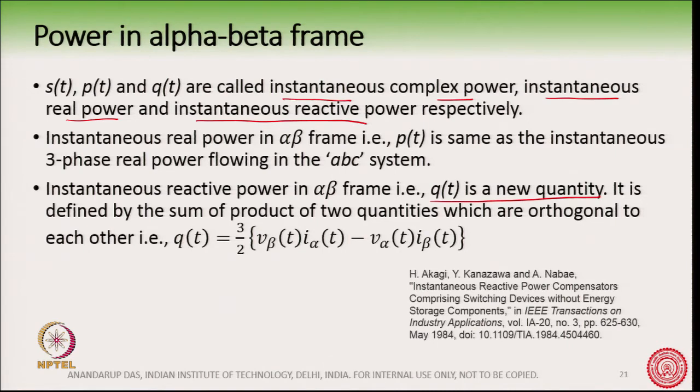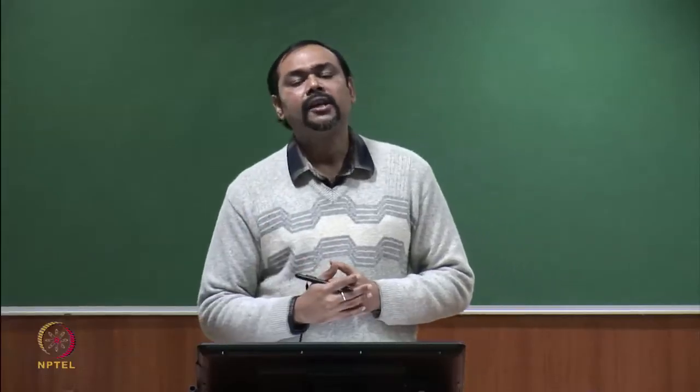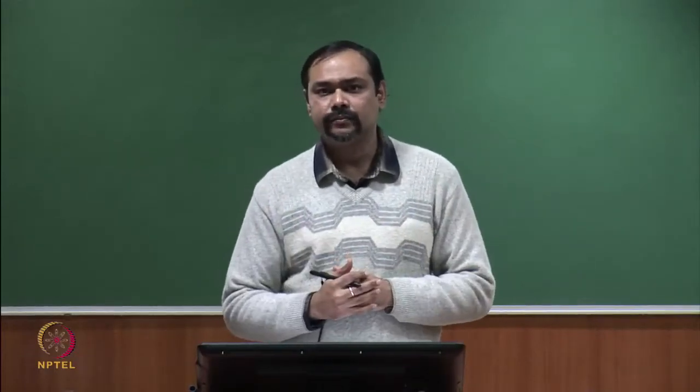Now, why are we defining this Q t as a new quantity? Because basically the traditional definition of reactive power has historically been developed for steady state balanced conditions.